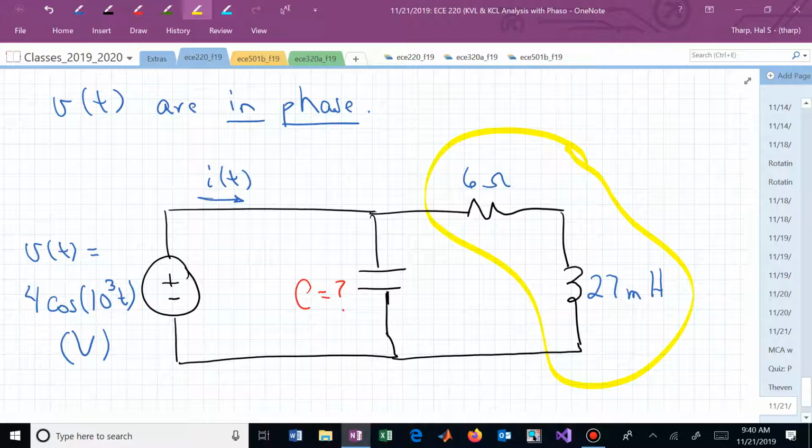and you're actually trying to reduce the cost of powering that motor. And so you're saying, you know what, maybe if I connect a capacitor across those two leads close to the load, close to where I am, the power company won't have to supply as much current as if that capacitor was not there. So let's see if we can make sense of that.